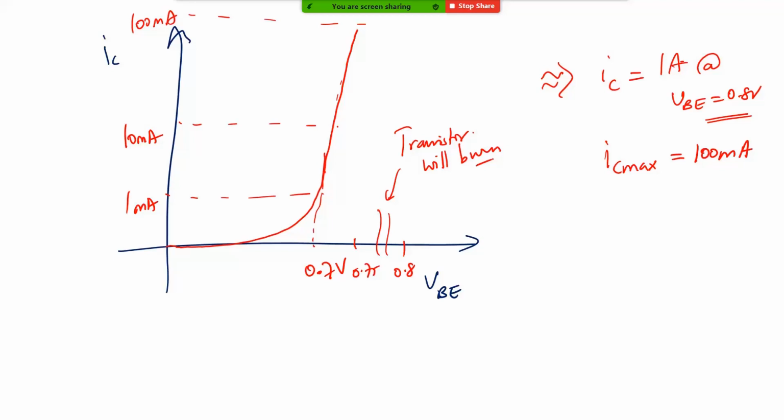So a typical transistor doesn't allow a large range of VB values. The voltage across the base-emitter junction is typically restricted to just small changes around maybe 0.6 or 0.65 or 0.7, which is why we just take that to be the nominal voltage and solve or design circuits.